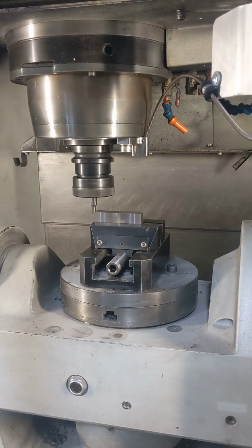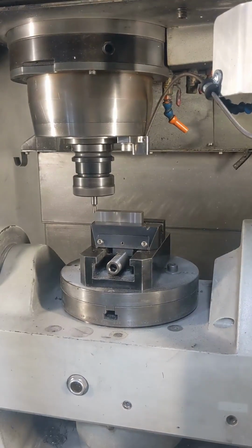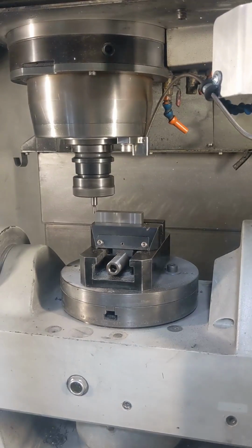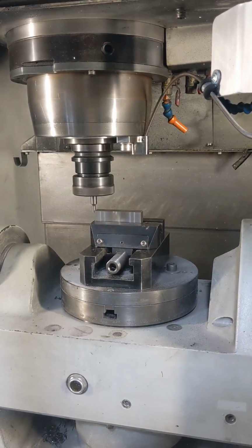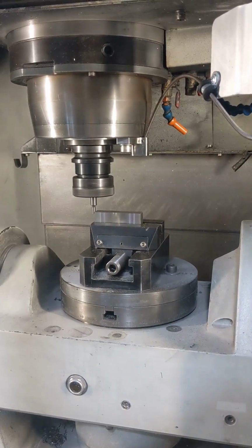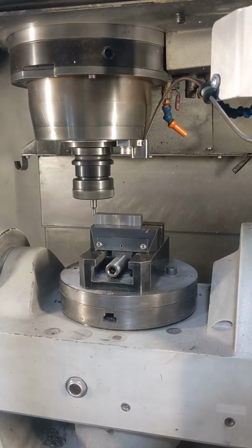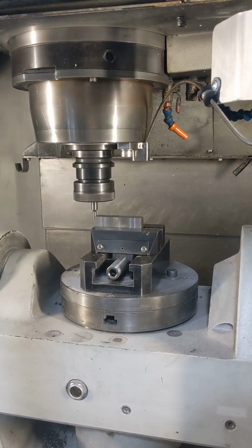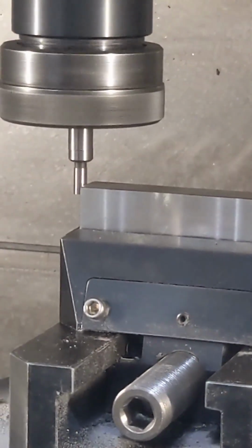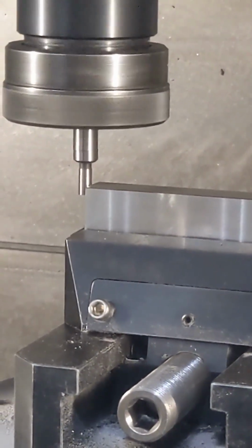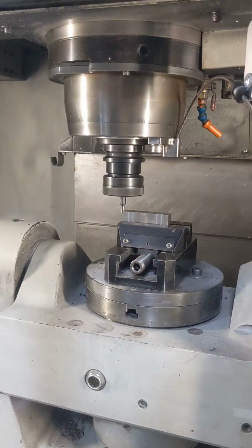If you're not familiar with edge finders, I suggest you go next door into the machine shop and play around with them a little bit. They're fairly easy to use. It is more difficult in this machine because we can't see the edge finder step off to the side in the x-axis, but it's definitely feasible. So I've just found the x-axis where it steps off to the side. It's difficult to see, but you can see there's a little bit of a step there.